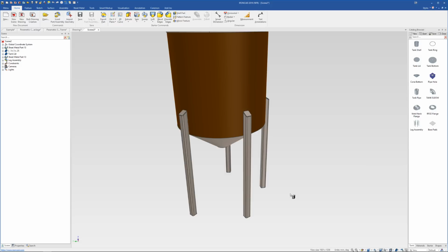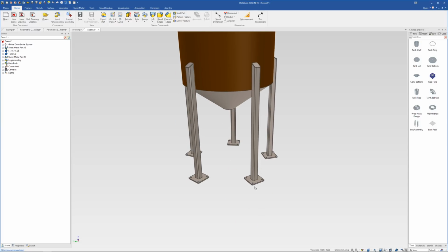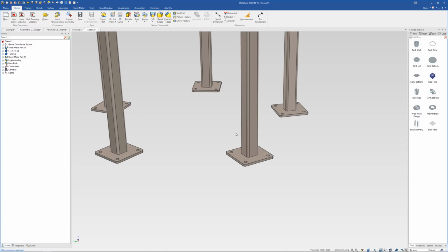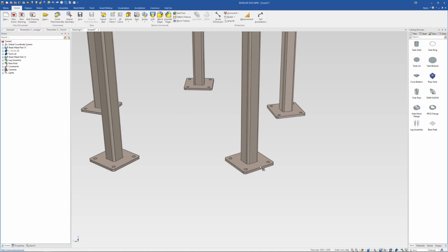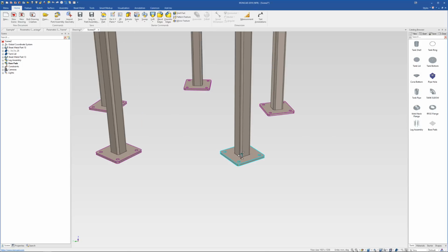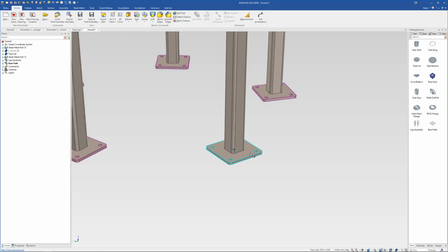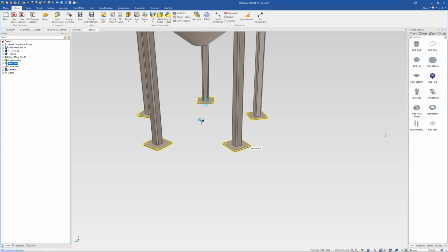Now, let's drag out this base pad, which is the main example I want to show here. Let's just say we want to swap out one of these base pads. This is obviously an entire assembly here, not just a part, but we're going to swap out the individual part. This is linked around, so it would swap out all the parts. But actually no, we may just swap out the one part. What we're going to do is swap this out with a control drag instead of trying to reposition a new one.